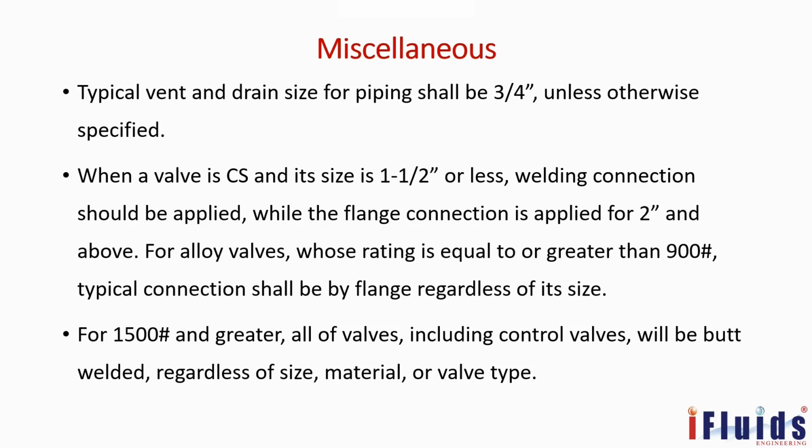For 1500 and greater, all valves, including control valves, will be butt welded, regardless of size, material, or valve type. If you are going to select a higher rating valve, the valve should be butt welded, regardless of size, material, or valve type.